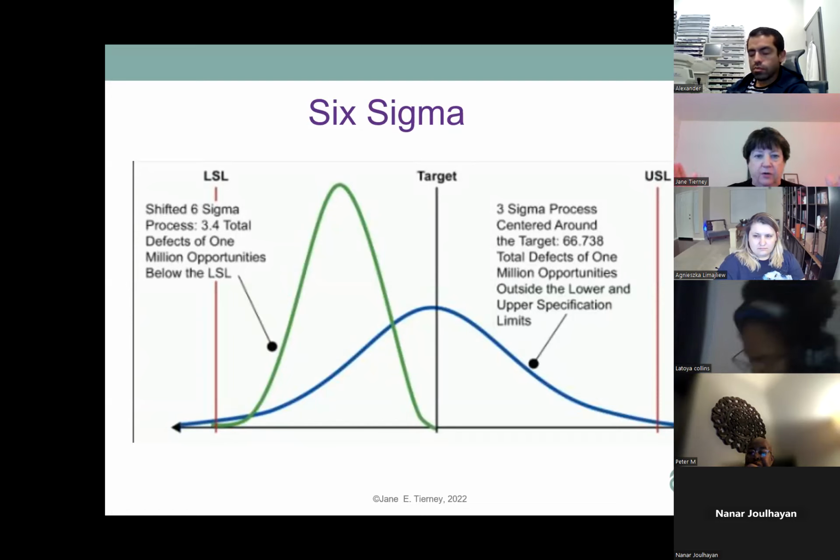So we're going to start with our target and our spec limit. We're going to design our process to produce products to that. And then we're going to measure it to see how much variation we have. And we want to have our control limits well inside our specification limits. Because we can have a process that's in control, but if we're outside of our specification limits, then that means we're going to have a process that's in control, but it's making parts that aren't going to meet our specification, and so aren't going to be usable in our process and our next steps.